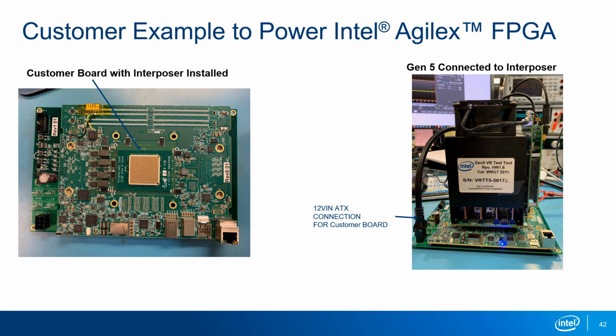They can visit you in your lab, connect it up, and inject large loads to see what your power supply transient response is. It'll measure the ripple voltage and then also the DC voltage accuracy. There are a suite of software tests, and once it's set up, you can completely characterize your whole power supply in 30 minutes. The VRTT mimics your FPGA and tests your power supply.